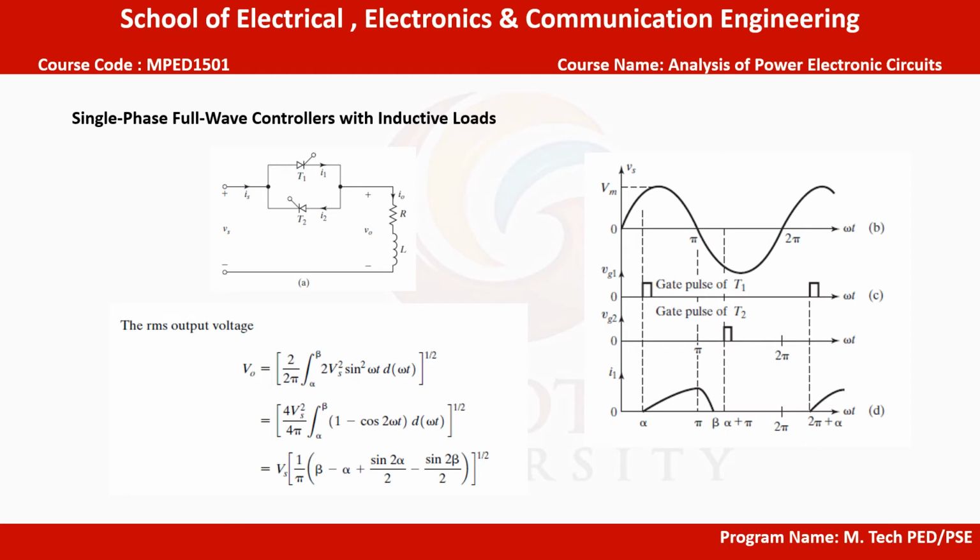The gating signals of thyristors should be short pulses for a controller with resistive loads. However, such short pulses are not suitable for inductive loads.